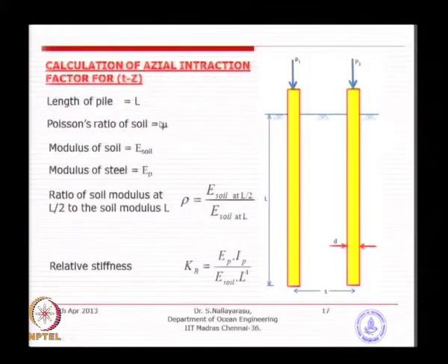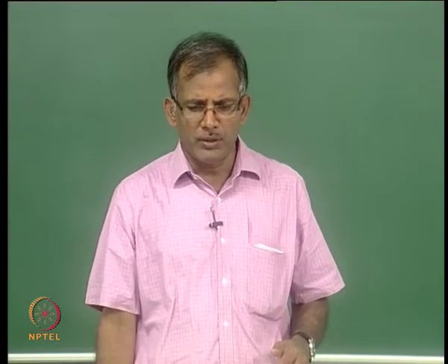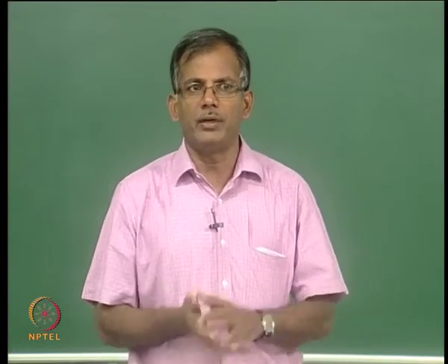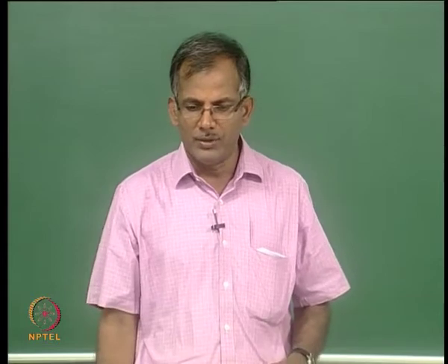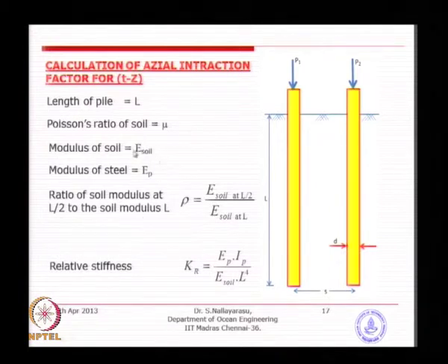In this principle also the modulus value plays a major role, because you can see the effect on settlement. So, an approximate procedure needs to be developed for computing the soil modulus. What we normally do in practice is carry out a separate analysis at various load levels, find the displacement of the pile, and then calculate the value of the soil modulus for the multi-layered soil. But in a classroom exercise it is very difficult, because without a computer you can't do it. So, in our exercise, you can take an average value in a multi-layered soil and use it for the computational purposes.